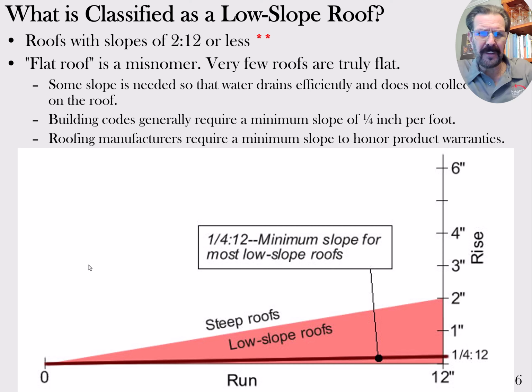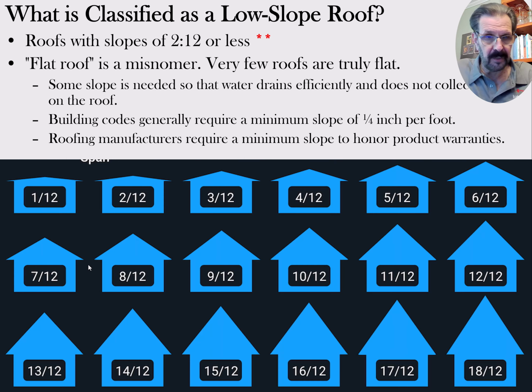Another thing we should shy away from: be very careful and beware of anybody who starts talking about roof pitch, because it's a nebulous, confusing concept. If you look at these roofs back here, the pitch is the overall rise divided by the overall span of the building, and that is really a meaningless number. In comparison, one slope to another, they can have some meaning, but a lot of people, when they say roof pitch, really mean roof slope.